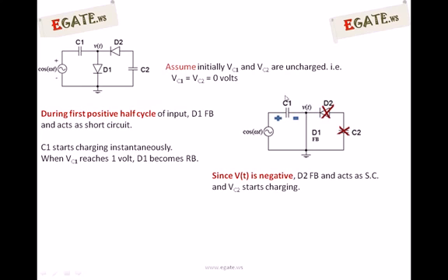because the effective voltage at the P side of diode 1 is always negative. Observe this. The capacitor voltage is constant at plus 1 volt, that is minus 1 volt in this case, and cos omega t values are in between plus 1 and minus 1. If you take KVL over this point, this potential V of t is always cos omega t minus 1.